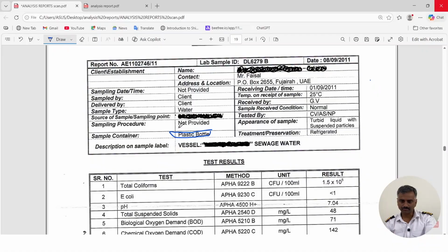So there, if you are doing it like a test, you are discharging the complete chlorination chamber and then fresh sewage, or fresh effluent, is coming into the chlorination chamber, then also your chlorination amount will come less. So make sure that your chamber is filled for some time and then you are taking the sample. Okay, if you are taking a fresh sample then there will be a very low chlorine count in that. So these are some of the nuances that you have to keep in mind.